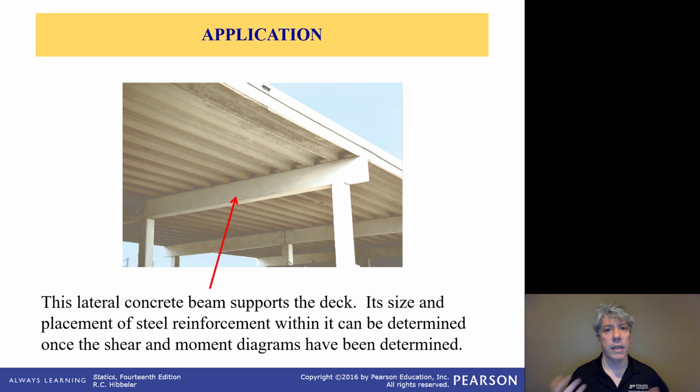How do you go about calculating the shear and moment within the beam if you have a lot of external forces or moments, or even distributed load, applied to the beam? What do you do? Because you really need to understand how the shear and moment vary within the length of the beam in order to determine where to put reinforcement, how big the beam needs to be, and so forth, so that it does not fail. So how do we deal with this?